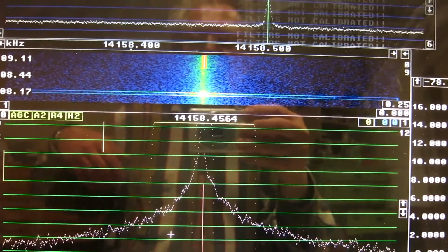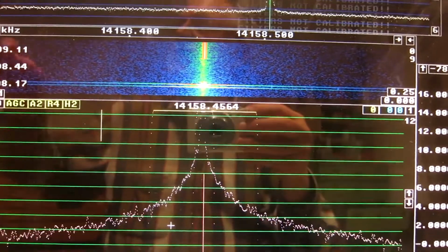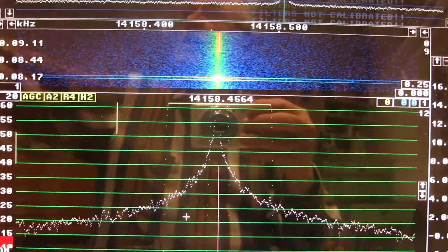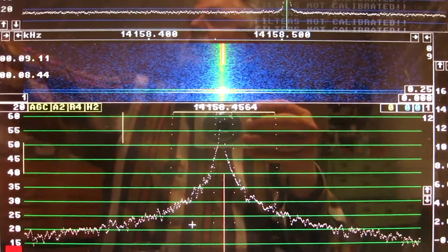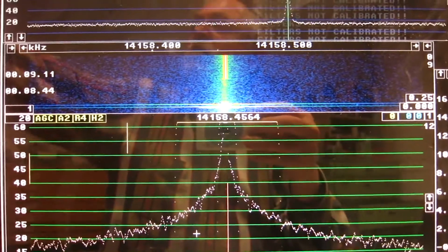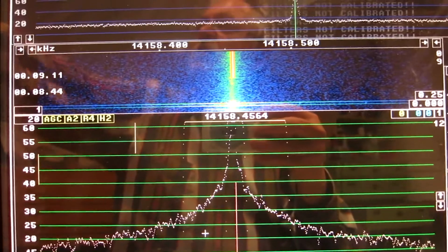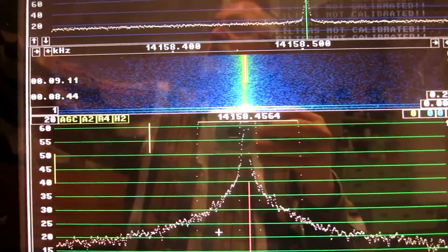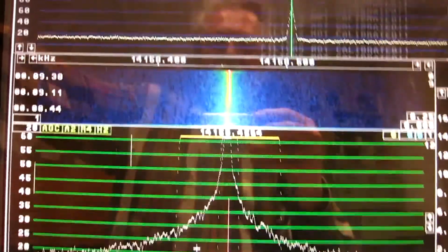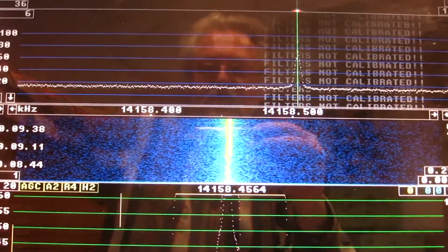I had to change the generator because I need 1 Hertz step, and even that is not perhaps quite fine enough. So this is minus 100 dBm. I increase the level. Increment set in the steps of 10 dBm. 10. And you can see on the waterfall the carrier becomes stronger but the noise doesn't change.